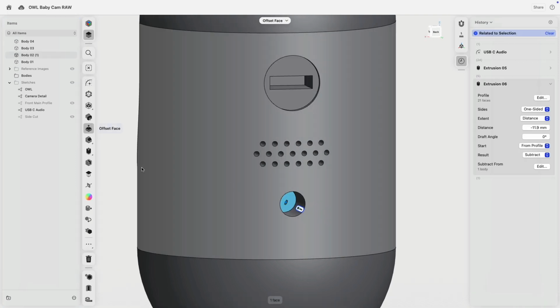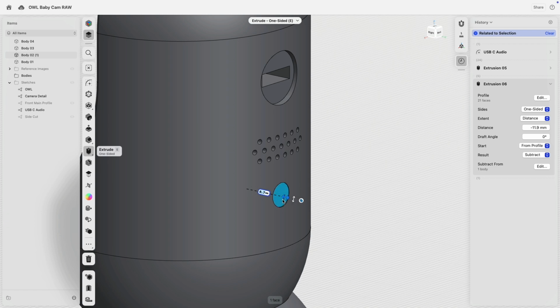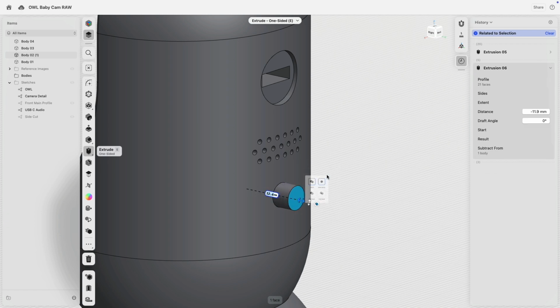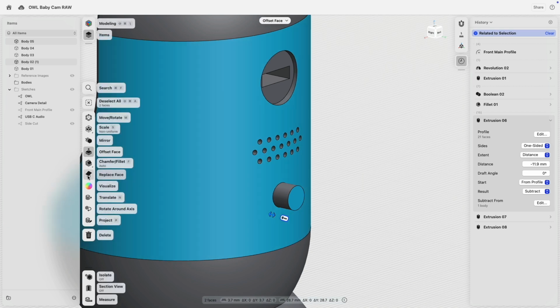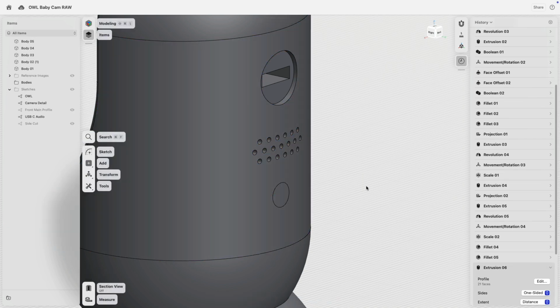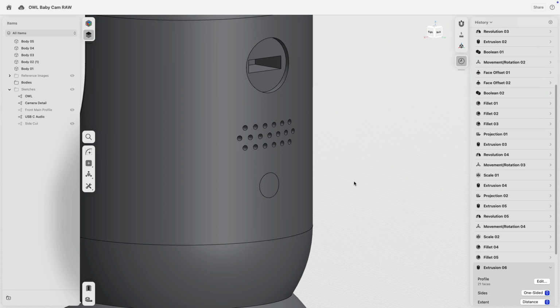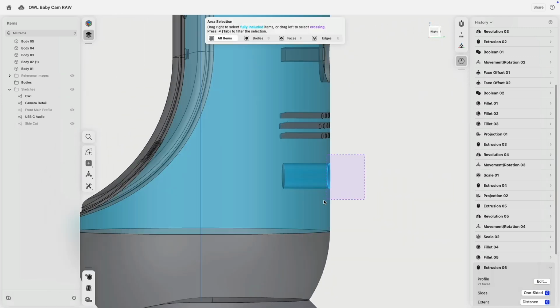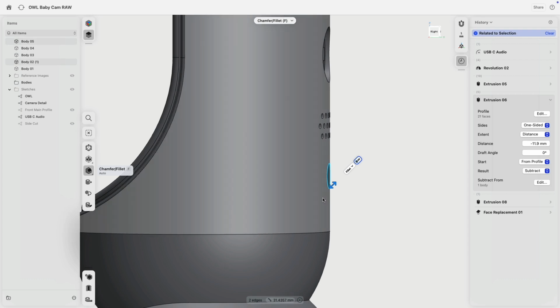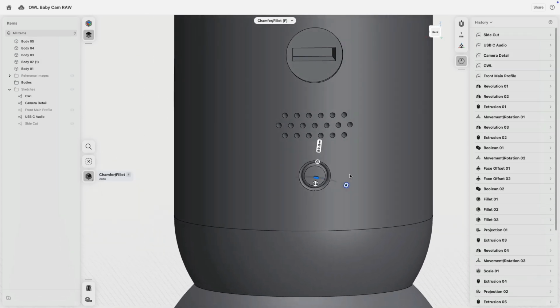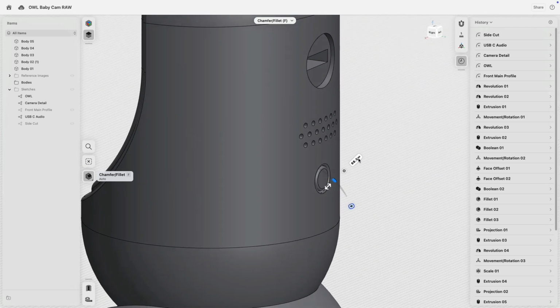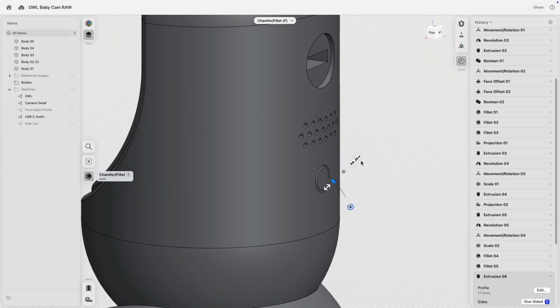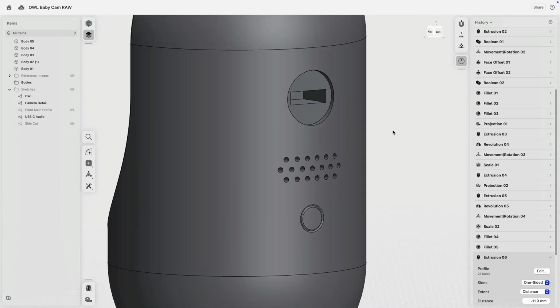We would like to build our button. I extrude this button out, very important, as a new body. And then this front face, I will match to that curvature with the replace face command. There we are. Now we can select these edges and say 0.5. How is that? That looks pretty big. Let's go 0.25. That feels better.